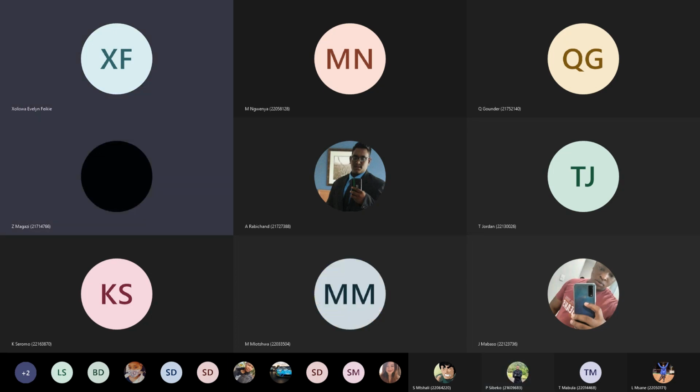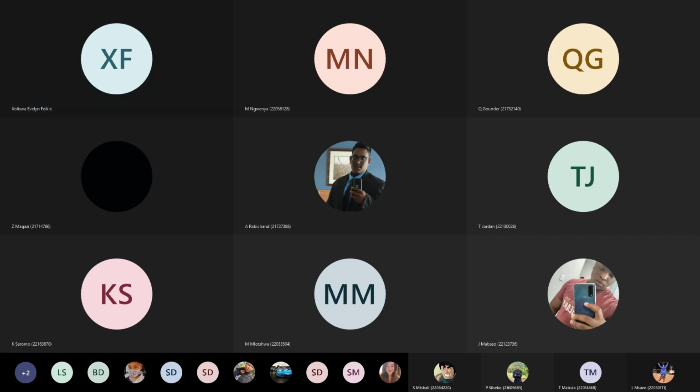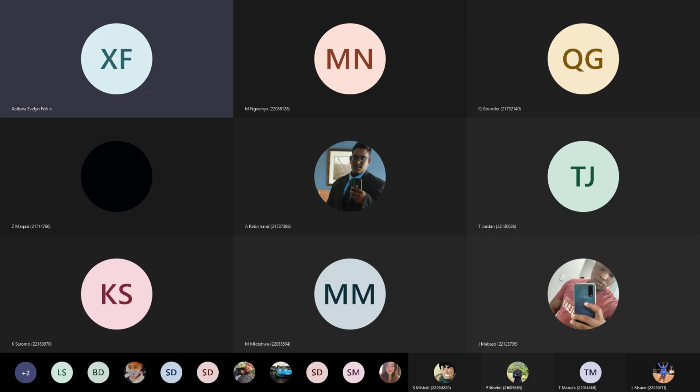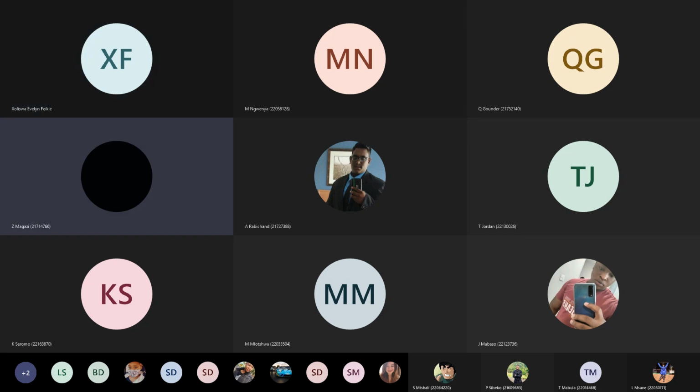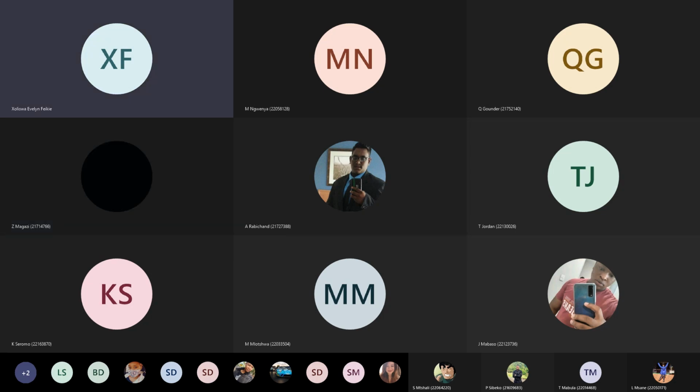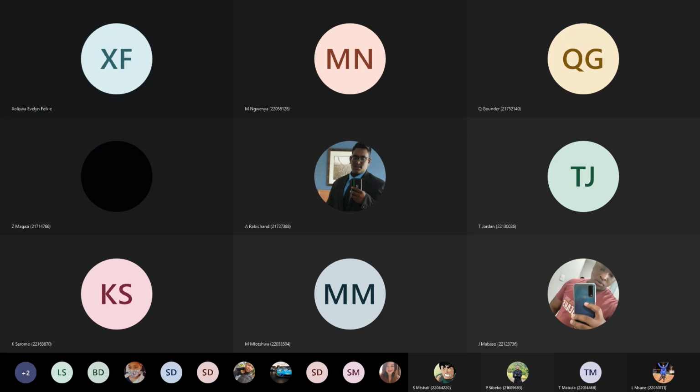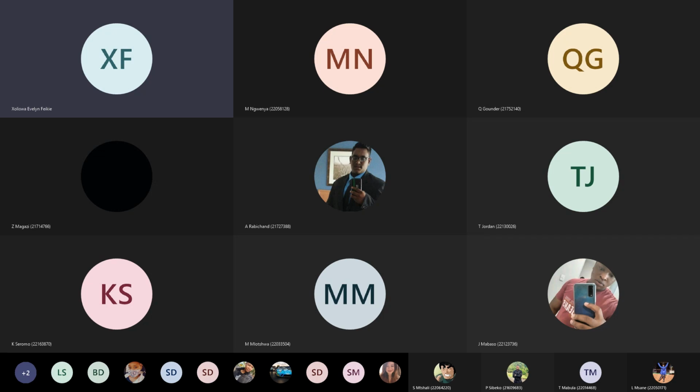210. 210. Okay. Do we need to make any adjustments? Yes. Why? Because the slump is moving from 75 to 90 millimeters. Okay. Look at your table and try to give an approximate number. How many liters do you think we will need to either add or subtract? Do we need to add or subtract? And if so, the amount of water?